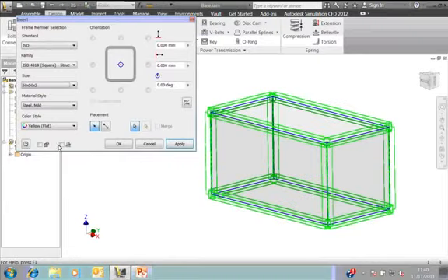So there are two buttons down here that are important to talk about. The first one is to prompt for the file name. Now, what will happen is the steel sections will be given a random numbering scheme to create a part number for the steel section. It will use the ISO description in this case as well as the start of the file name. But if you actually want to be prompted for the file name yourself, so you can put in your own part numbers to these, then tick that box there.